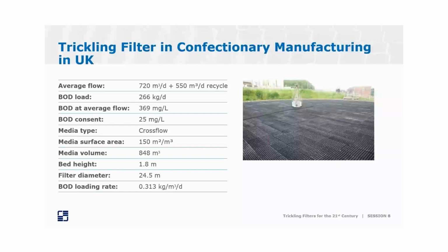And being 1.8 meters deep, that's about 6 feet, the cross-flow action gives you more retention time than just using cross-flow and vertical flow media. That would be the normal case on higher deep bed filters with higher loads.